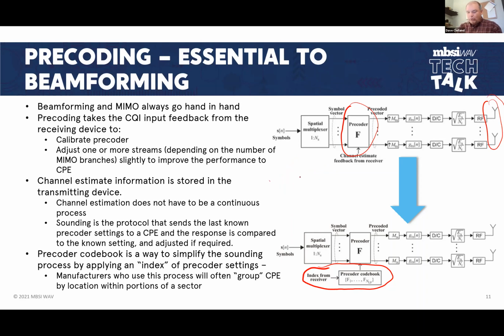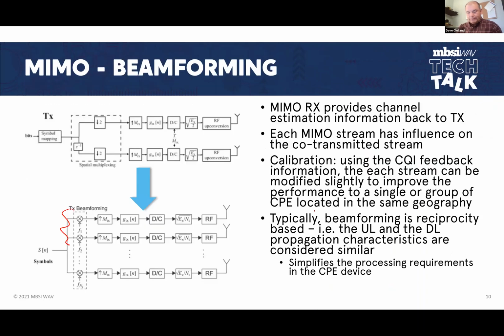The point of all of this is that I can replicate my MIMO settings any number of times, right? As many times as I have dual ports on my antenna. So if I had 3 groups here, I can theoretically achieve 3 times the capacity that I have here. So if I have 3 groups, that's 3 times what I can achieve with one MIMO group. This is the point of beamforming: now I can increase my spectral efficiency even more.